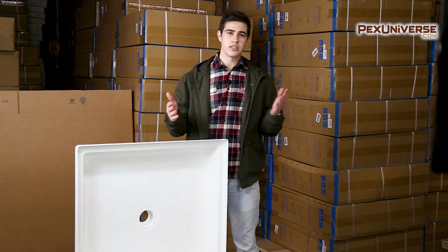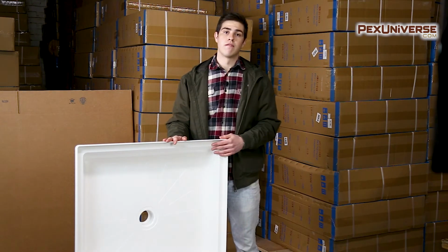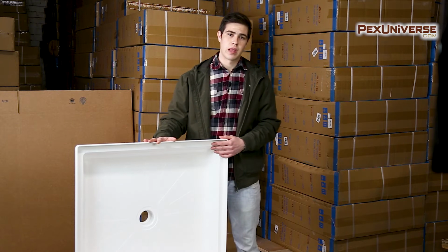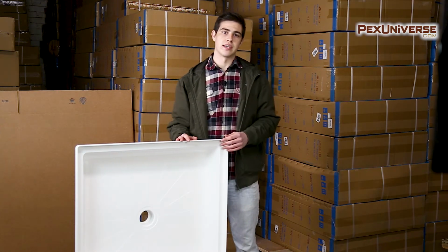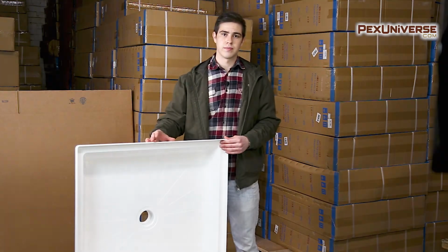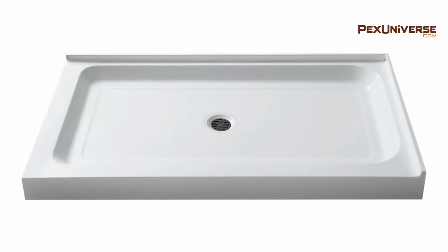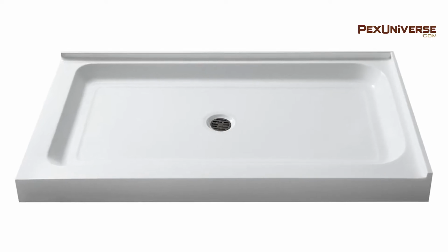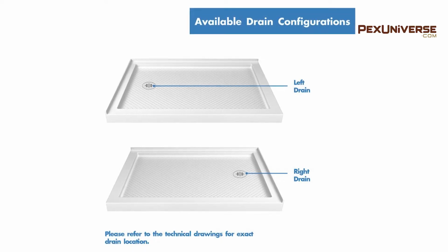If you are working within a certain budget or you want to install it yourself, then that's where these pre-made bases come in. First, we need to figure out what kind you need. Get your measuring tape, go to where you're trying to install it, and figure out the dimensions that you're going to need when you're choosing these. Where is the drain located? Most of the time it'll be directly center, but if your shower was previously a bathtub or piped for one, then we have bases where the hole is to either side to help alignment.